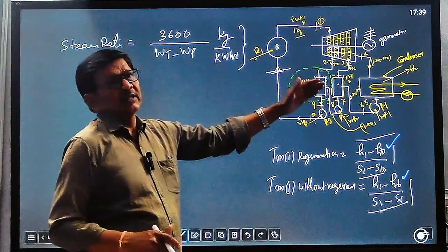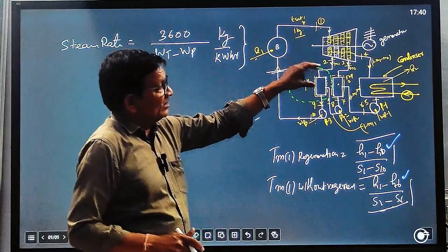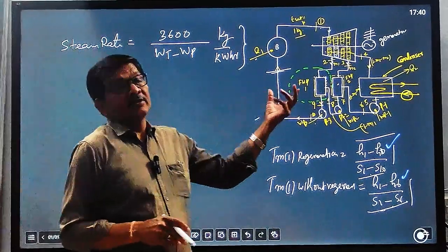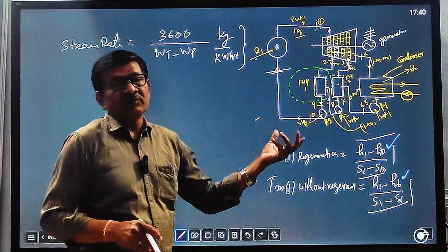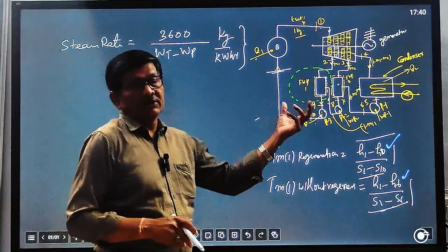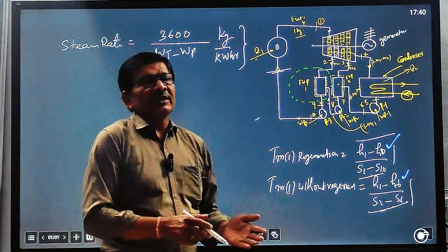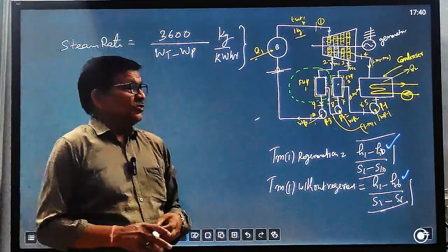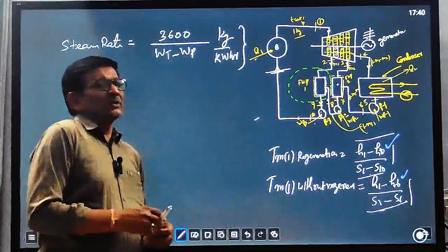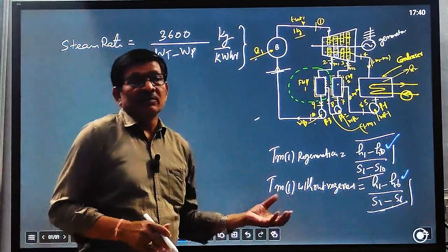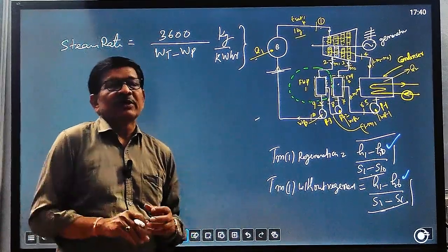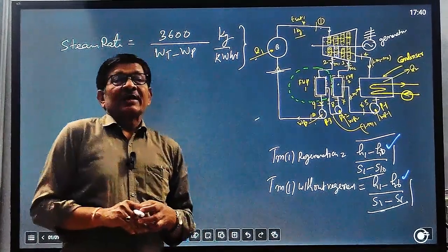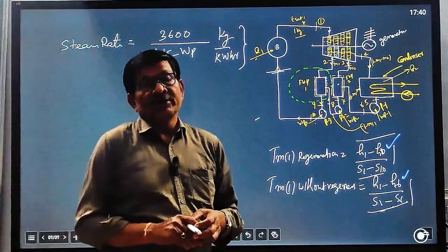The only thing you have to learn is how to apply the energy and mass balance equation, which is the first law of thermodynamics. You know the law of continuity, mass will remain constant, and you know from the law of conservation that energy is conserved. These two laws can be combined together, and it becomes the energy and mass balance equation. Once you practice 2 or 3 questions, first you have to be careful about taking units, because units are very important. 50% of mistakes students generally make are due to lack of practice and lack of knowledge about units.